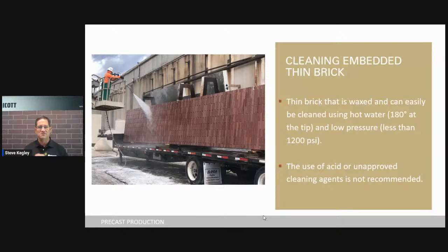But we've done tests at the plant in the lab with concrete embedded thin brick in concrete, and they've played around with the different percentages of acid, and it can do some major damage. And it's not just to the brick. It gets into the concrete. Believe it or not, it will get into the concrete, and it can cause some major issues in there. It is very eye-opening. So please use approved cleaning agents.